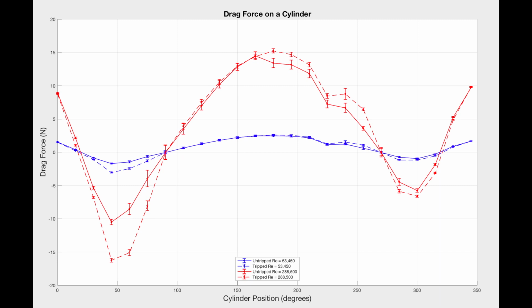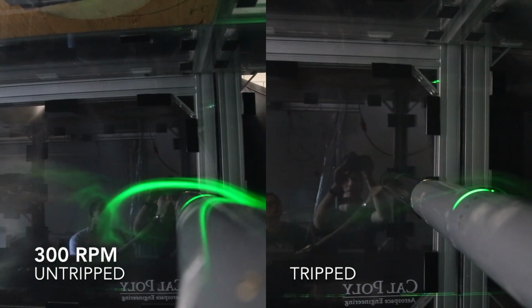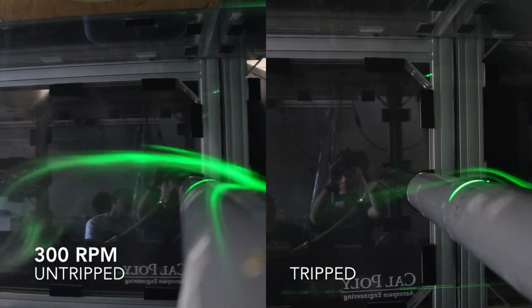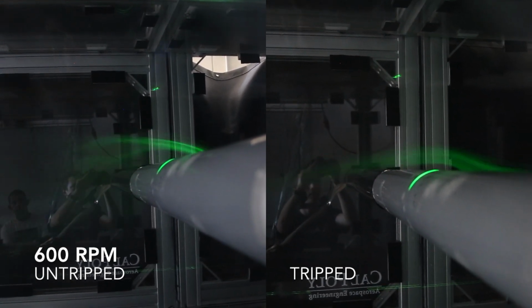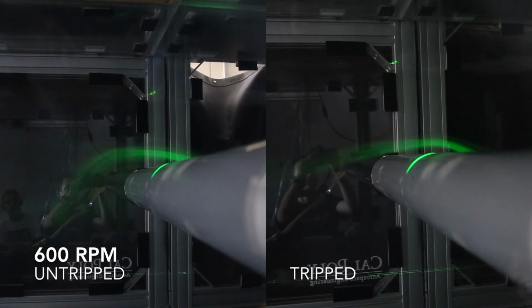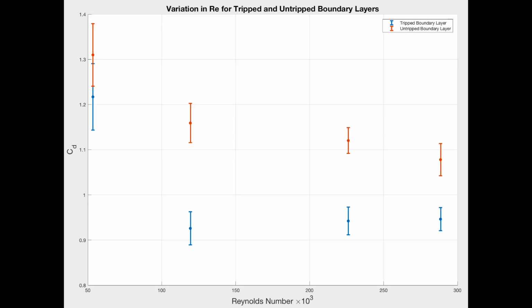The drag plot should appear to be a cosine shape symmetric about the x-axis, which would result in a net sum of 0. However, because the flow becomes unattached at the back of the cylinder, there is a low pressure region in the back, which effectively pulls the cylinder back, and results in a non-zero positive net drag force. When the boundary layer is tripped, the flow stays attached longer and more closely resembles the predicted cosine shape, and results in a non-zero but somewhat smaller drag force than that without the tripped boundary layer. The difference in total drag can be seen in the plot of CD versus the Reynolds number.